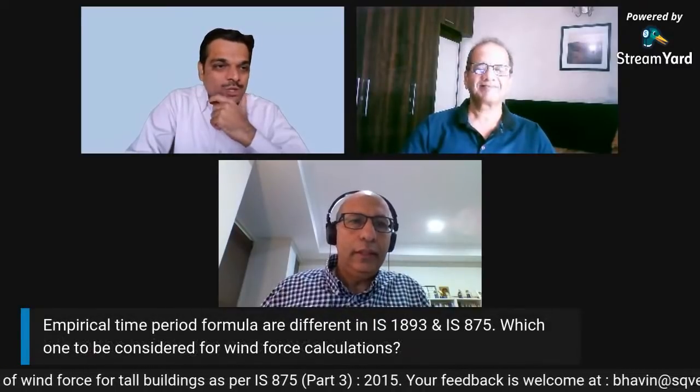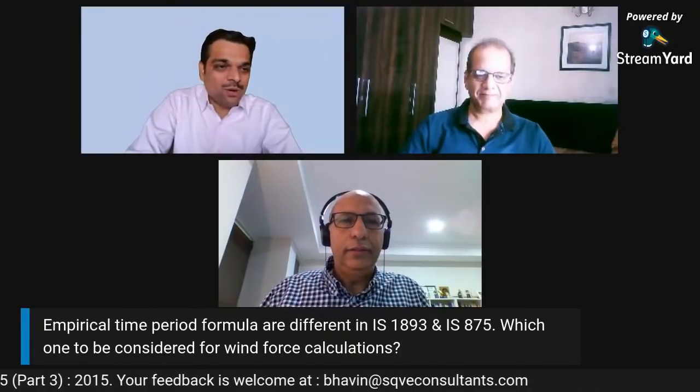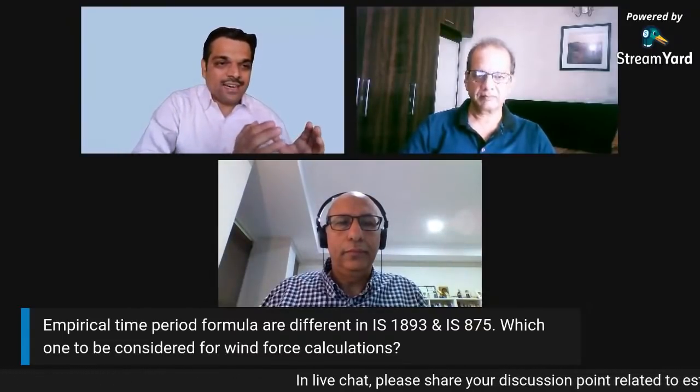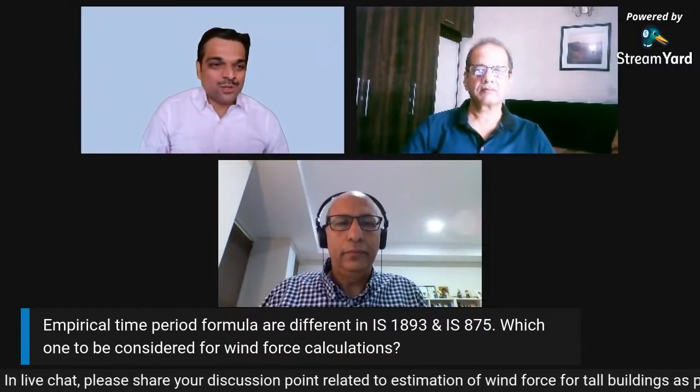Right. Another interesting question we have received. I think we have already touched upon this area, but the question was: when we talk about the empirical time period formula, it is different in earthquake resistant design codes and different in the wind codes. So which formula should we refer to when we are calculating the wind force? That was the question.